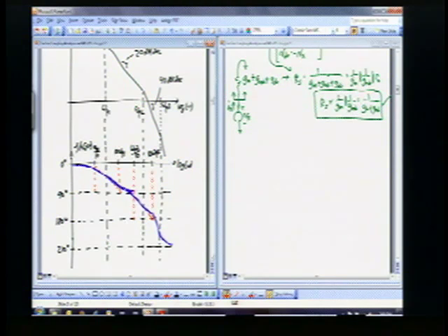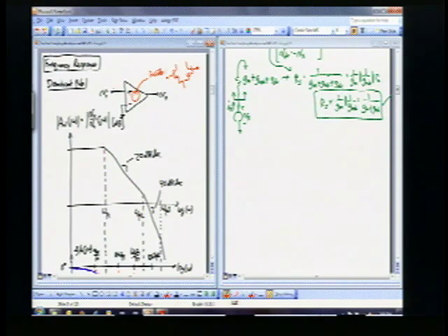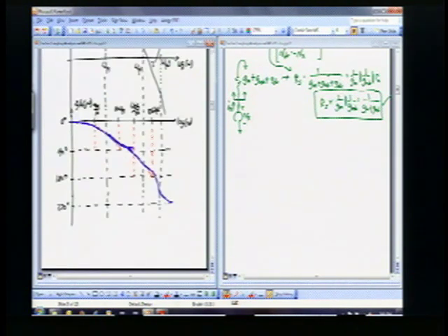And so remember, we're talking about an op-amp here. So we're talking about this device here. When we put this in negative feedback, we want to have a stable circuit. But if you put it in negative feedback, and because of these phase shifts, you actually end up with positive feedback, which is what happens if you're operating at a point where the amplifier is 180 degrees phase shift, you're not going to have a stable circuit. It's going to go unstable. Okay, I'm saying a mouthful right now, so if you don't understand what I'm saying right now, then don't worry about it, because we're going to spend 2 weeks on this towards the end of class. Okay, but stability is a big criterion.